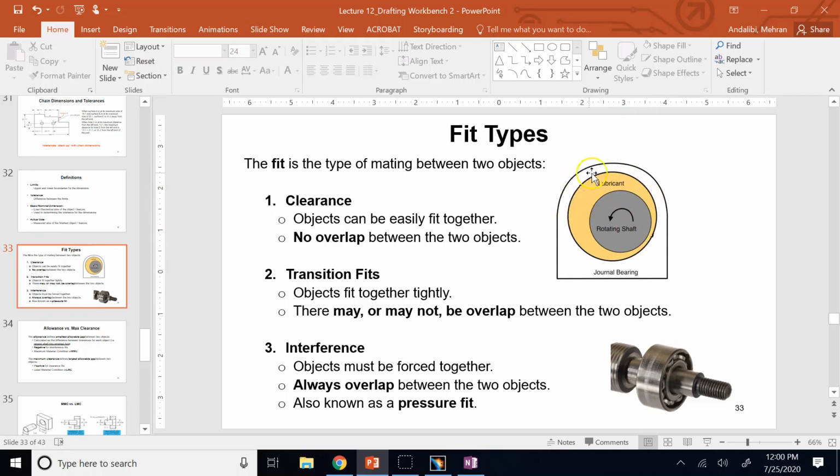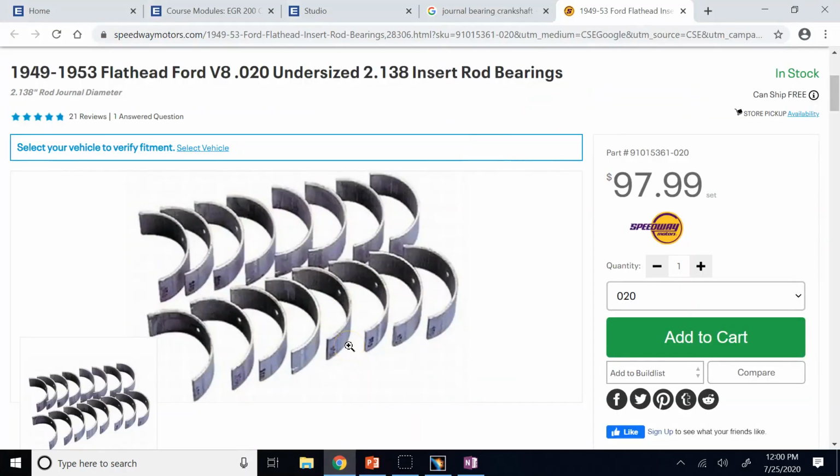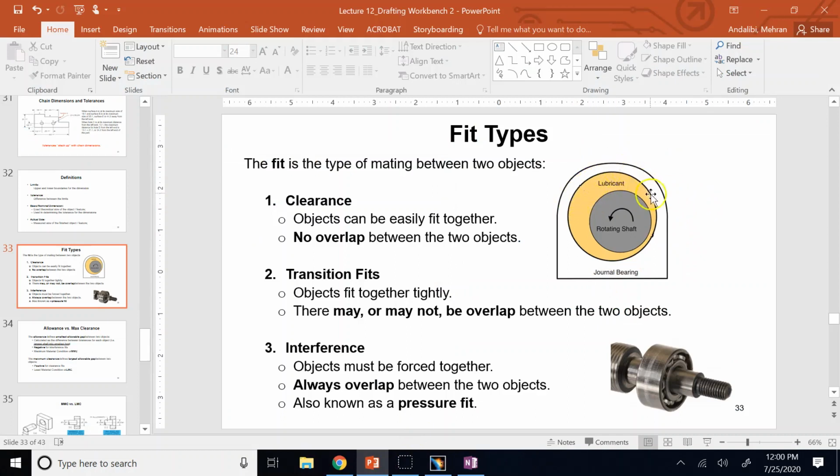Also the inner body of this hole is covered by a type of alloy that is really resistant to corrosion and erosion. We call them bushings, like these. These two pieces of alloy, these two semi-cylinders, will come and get what? One of them covers the top part, one of them covers the bottom part. As I said, they are really good against erosion. So if the shaft touches them, they are not going to wear out very fast. They are really resistant alloys.